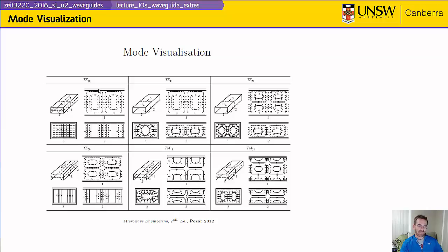As this magnetic field circulates, it needs to be supported by a time-varying electric field, or displacement current density. So at this instant in time, I've got this circulating magnetic field. That circulating magnetic field will cause an electric field to grow. And as that electric field grows, the energy from the magnetic field will move into the electric field. Likewise, this electric field will give rise to a local magnetic field, and so the energy will slosh back and forth between the electric and the magnetic cases as it goes down the line.